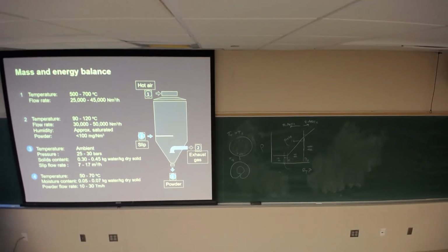suspension to be maximized. Why do you maximize the solids concentration? Yes, but the product is, you could say, greater throughput, but the real reason is cost. Because it costs money to evaporate water. The less water you have to evaporate, the less your cost is. And then for the same amount of energy cost, you make more product. So yeah, there's a product thing, but it's really about cost.